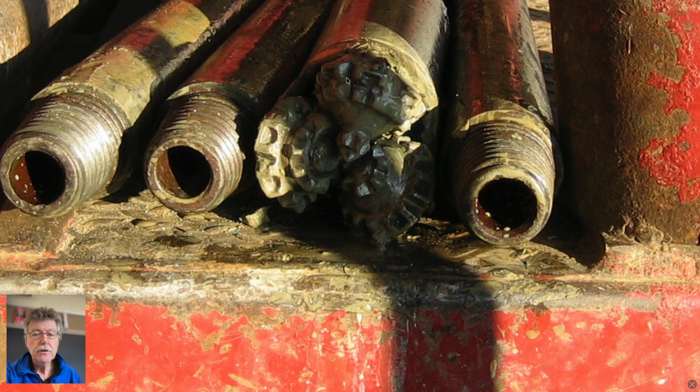So as a result of that, you can imagine that these tricones just run over like wheels at the bottom. But these tricones have little cutters on them. They're usually little buttons, like a button on a jacket, less than 1 inch across. And this is pushed so hard into the bottom of the hole that it fractures the stuff underneath them as it rolls over at the bottom of the hole.